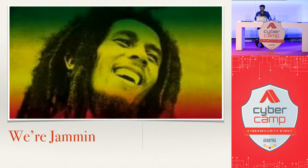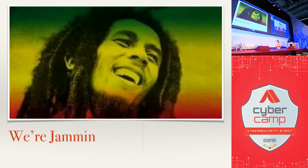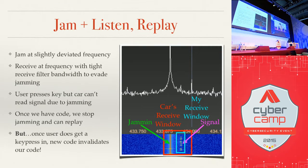So how can we actually exploit this? Is there a way we can exploit this rolling code? And we can, with jamming. What's interesting is, let's take a look at this graph here. The red square is the car's receive window. We have frequencies on the x-axis, and the car receive window is pretty big. Let's say the car listens at 315 megahertz. Really, it's probably listening between 314 and 316 megahertz. So you can transmit the data anywhere in that 2 megahertz of bandwidth.